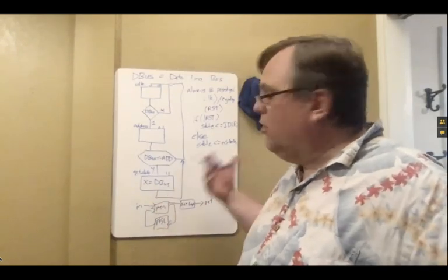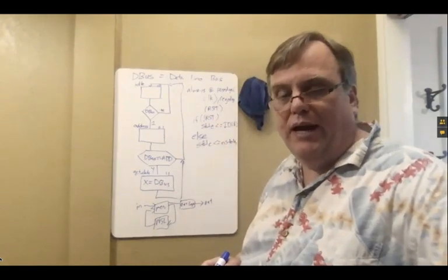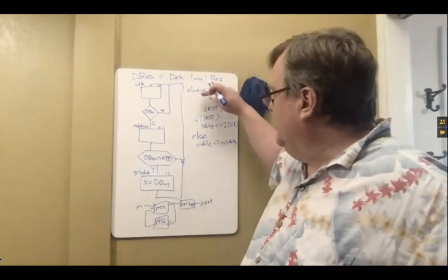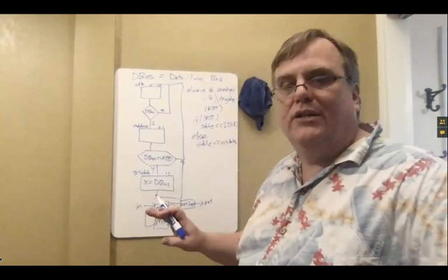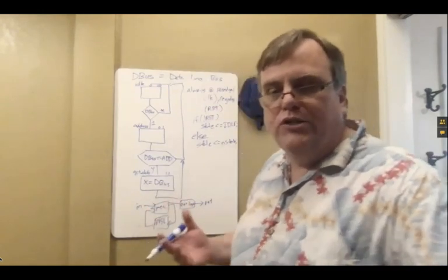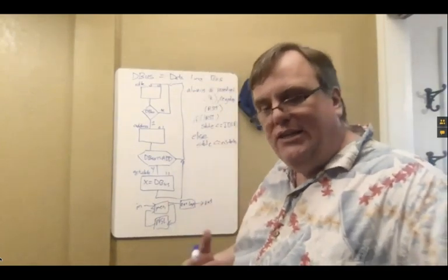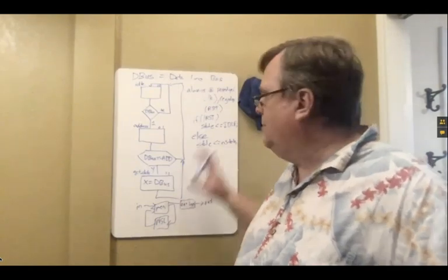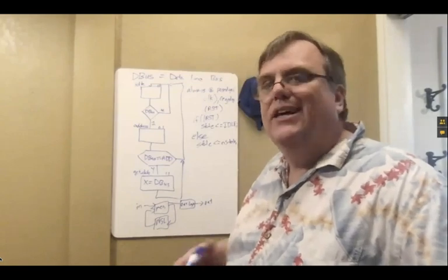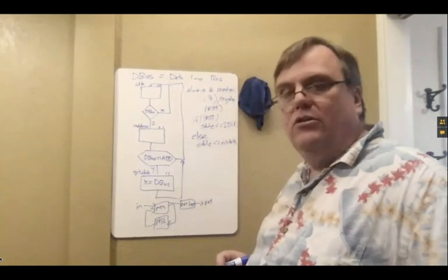So if I have larger pieces of memory, if you follow a very standard memory template every time you access memory, it can allow the system to know what type of resource to pick. It would say, oh, this is only a memory action, I can pick one of these memory blocks instead of picking a logic block. Depending on what resources it has available, following a convention like this just makes it easier for the system to infer what type of thing you're trying to build. So it'll pick the resources better automatically. That just gives you a better design. All right. We feel good with that?